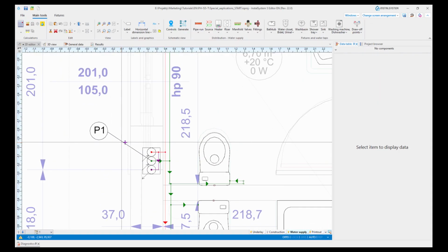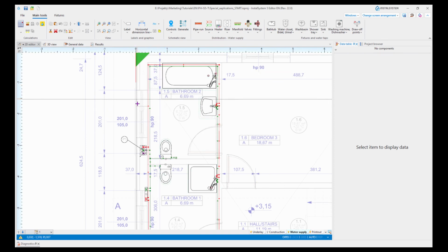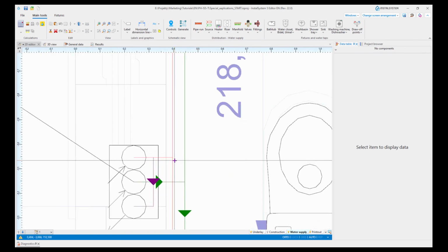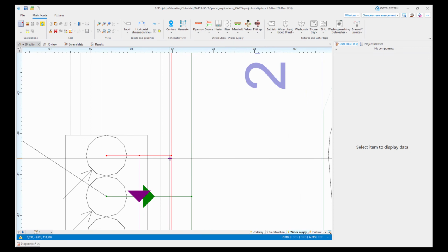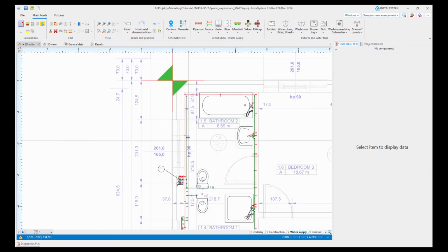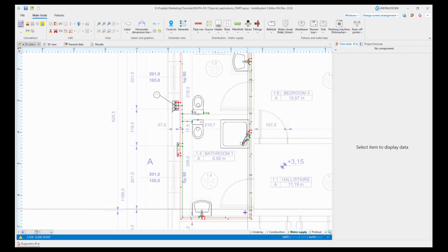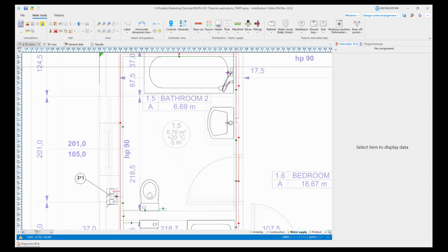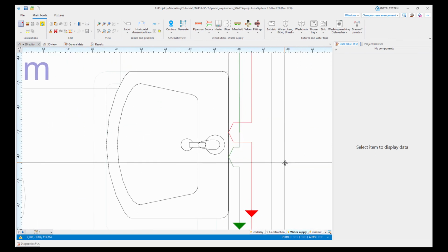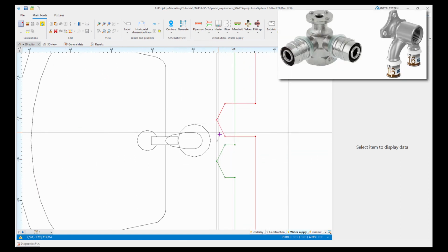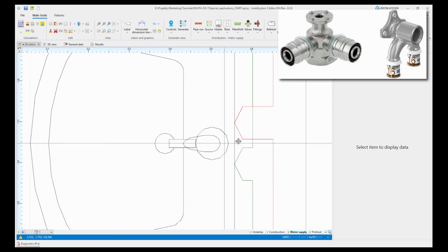And what are the rules of designing and calculating these ring installations? The ring must start and end ahead of the riser. So as you can see in this case, it starts here and the ring goes round through these 2 bathrooms. Additionally, we need to have in the database we use in our project, database of pipes and fittings, some additional extra T fittings.